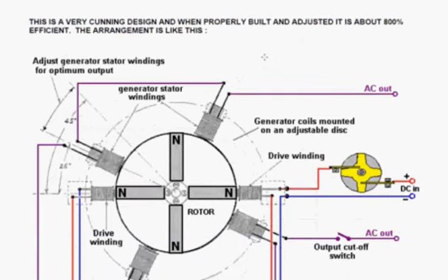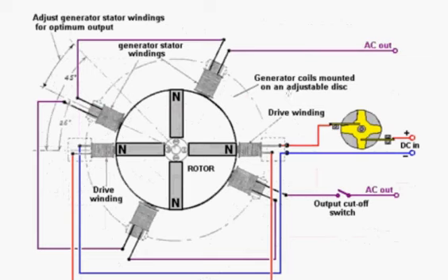The highest powered version of this that I've ever heard built and described outputted 32 kilowatts of energy, which powered both a business and a household for the person who built it. Now, it has got 4 rotor magnets. They're long magnets. The south poles are kept in the center of the rotor, and the north poles are on the extreme outside of the rotor. The drive coils and the pickup coils have got solid iron cores.